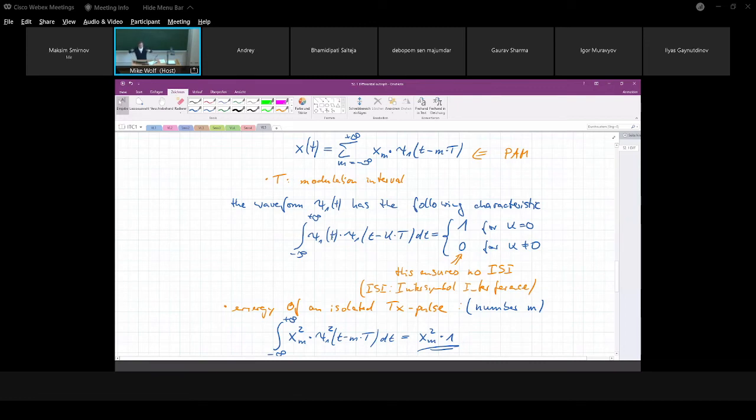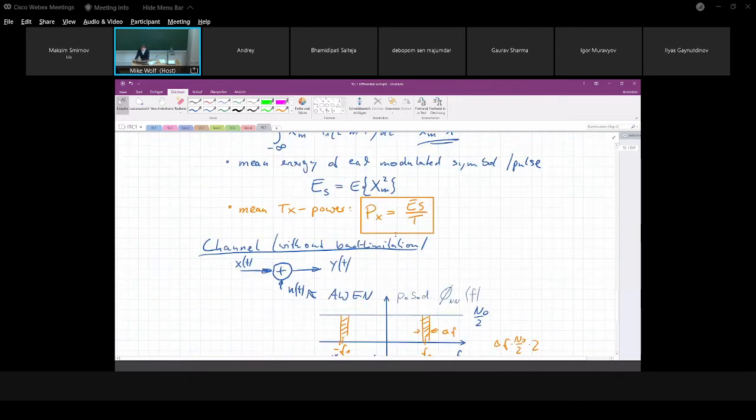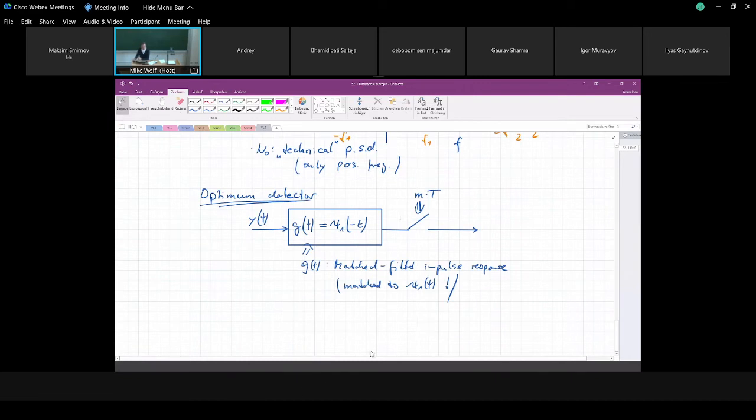But if you do the convolution, in the convolutional integral you have to insert one signal with a negative time index. So this psi1 of minus t becomes psi1 of t in this convolution. And this condition, what is written here, ensures that at the output of this matched filter, adjacent pulses do not interfere. I don't talk about noise.